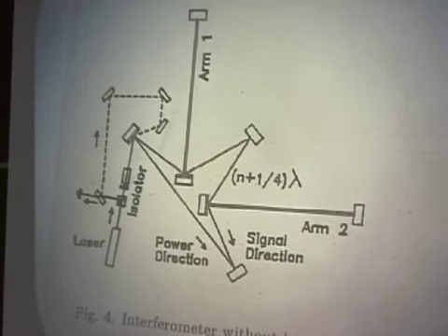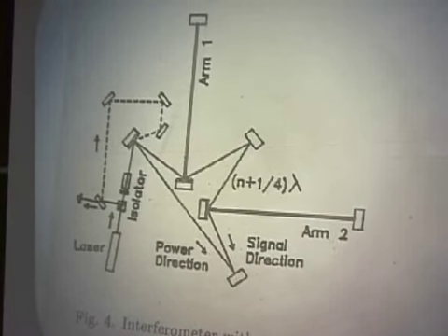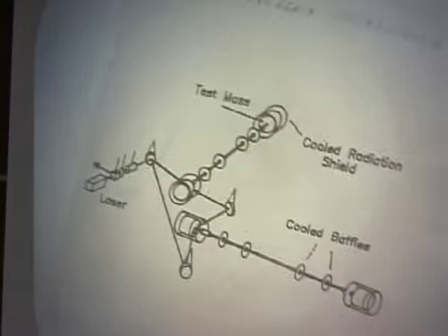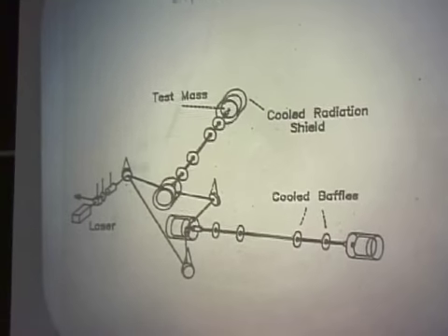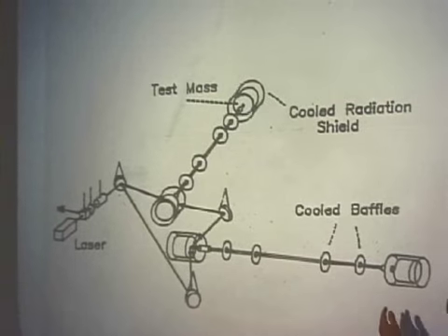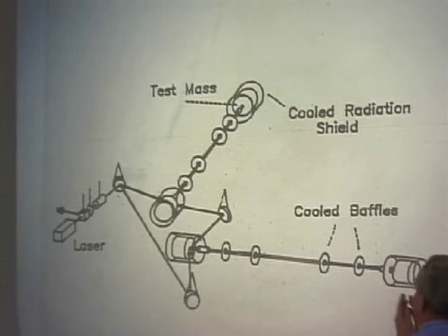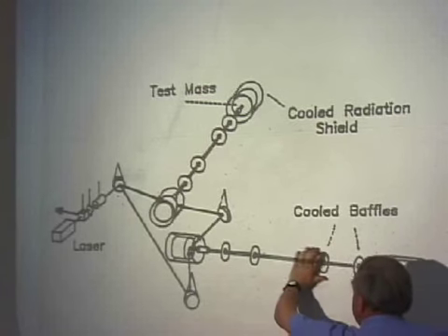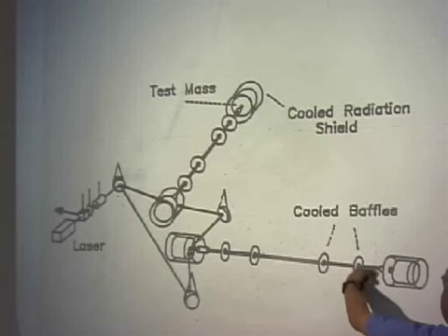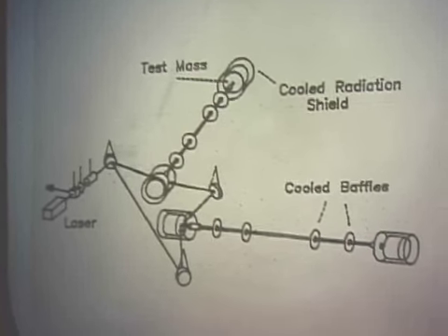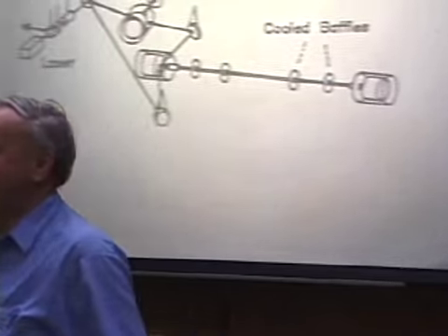And finally, I did show in one of the published papers I had on this, the first diagram I think I've ever seen in print suggesting a cryogenic interferometer utilizing the idea, because this would reduce the heating. Here I'm suggesting that there's a cold part here. There are baffles here to reduce heat coming in from the hot walls. I'm assuming that in this case the pipe walls are not cold, but this cuts out the heat input into the cold part here. So this may be something like that. That paper was a long time ago, and it's taken a long time to get to anything like reality, but that's a possible way of doing it. Okay.